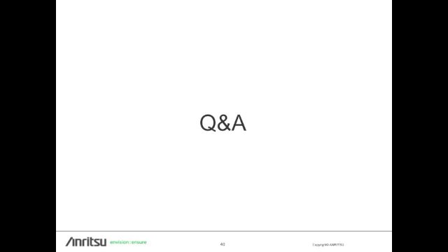Okay. Finally, well, we have time for just 2 more questions. So the next one, what are your thoughts on log periodic versus Yagi? It's one of those trade-offs. Log periodic, if I'm looking at a wide frequency range and I don't know what frequency I'm going to work at, is a good choice. It just doesn't have as high gain or as narrow beam width as a Yagi. So if I'm working on cellular, I might have 3 or 4 frequencies. A couple of Yagis to carry around isn't too bad. But if I worked for a regulator and I had no idea what frequency I was going to work at, log periodic is a better choice because I don't have to have hundreds of them.